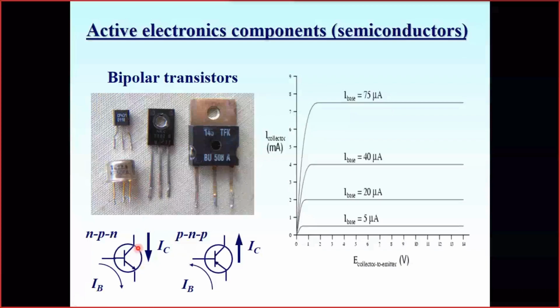The ability of the transistor to pass current through is dependent on the current through the base electrode. Let's remember we have three electrodes named the collector, emitter, and the base. If we provide current through the base to the emitter, then we will get a high current through the collector, of course, on the condition that there is some voltage source which can push current through the collector. The two types of bipolar transistors are named PNP and NPN, and it depends on how the transistor junction is made.